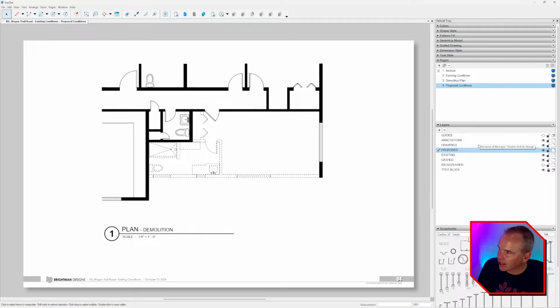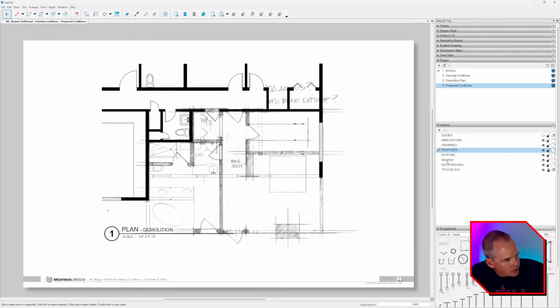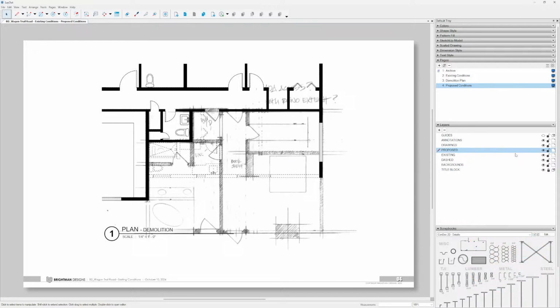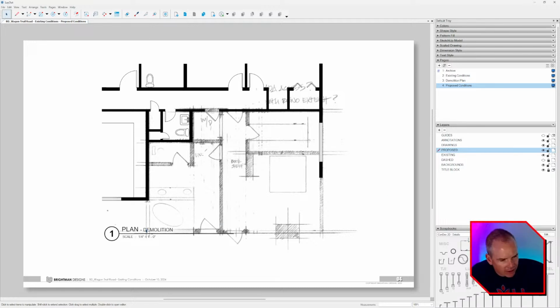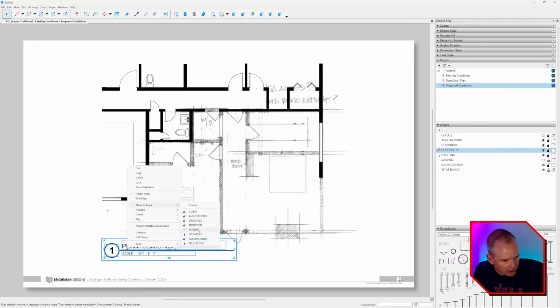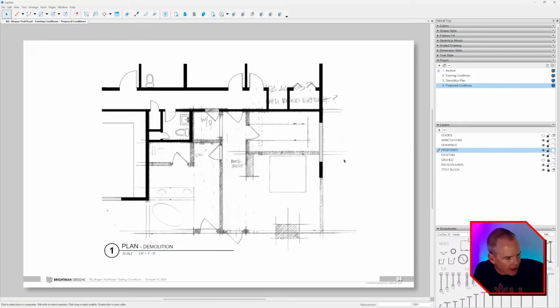And it's easy enough to break these, or trash these layers and move things around as you need to. So, all right, that's cool. And so now we can have our backgrounds turned on. And I think for this task, I would turn dashed off, lock that layer, and then let's nudge our annotation out of the way. I can right click and move to layer annotations like that.